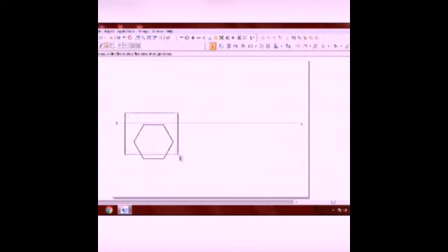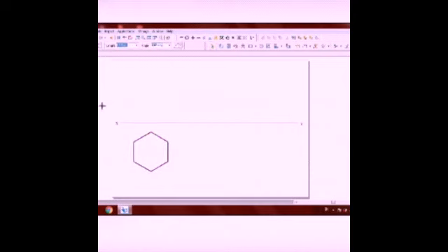You have to select the hexagon and rotate it using the rotate command. Select one of the points and then the edge, then rotate it. Switch off the multiple copy, that's very important. Now it's a pyramid, so go to the line command and draw lines representing the slant edges of the pyramid.